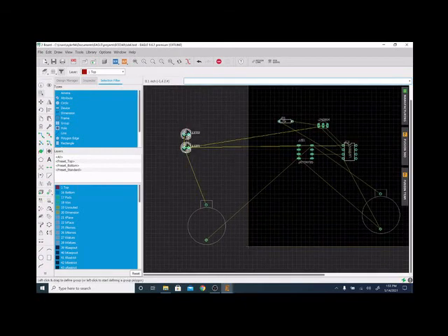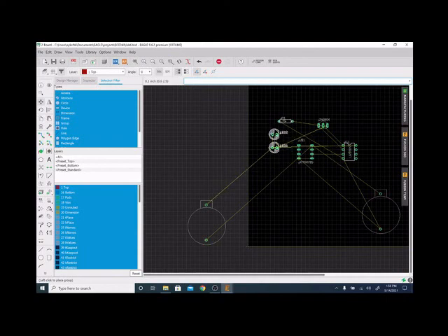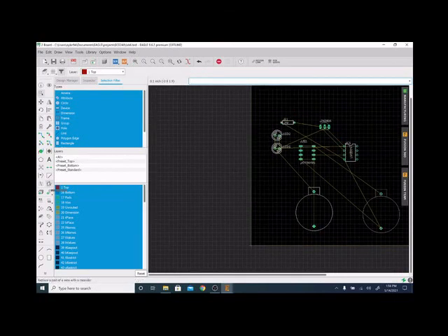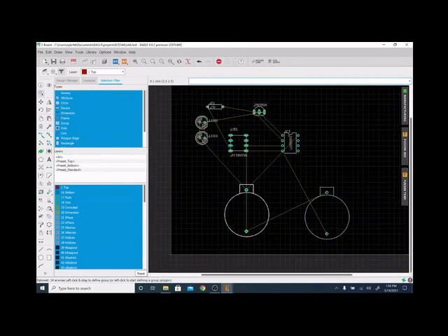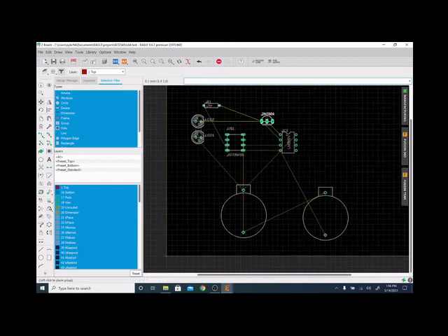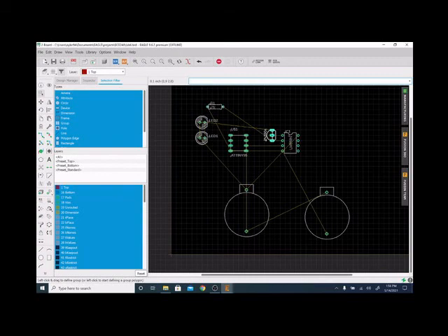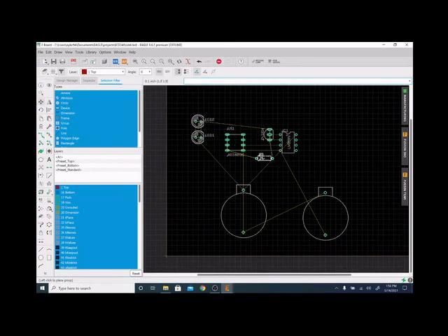What's nice is, though, we can use a tool called Rat's Nest to help us clarify what's going on. If I hit the Rat's Nest key right here, it will go to the most orderly, or optimized, layout. And you can see that cleaned it up quite a bit. All right, so I'm going to rotate that and put that there. And I'll take this guy and rotate it down here. What's a good spot for him? Oh, he's just going to the ground.